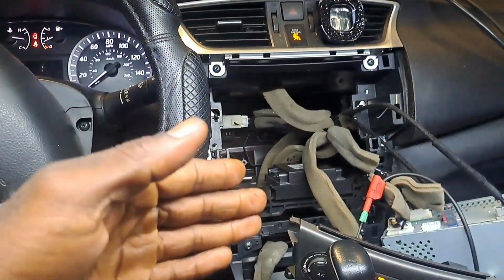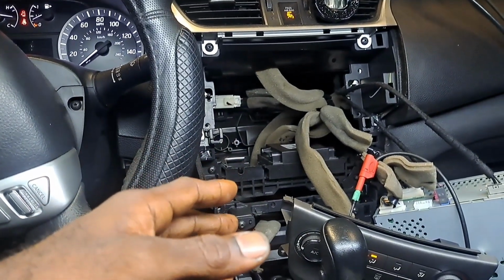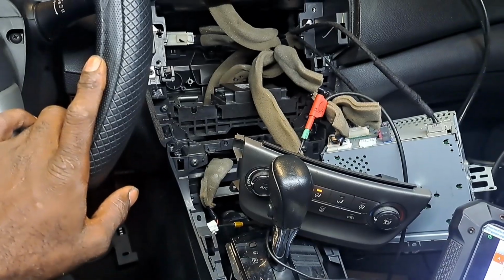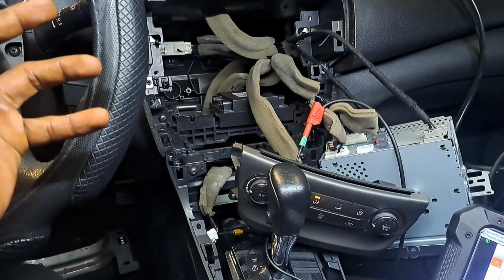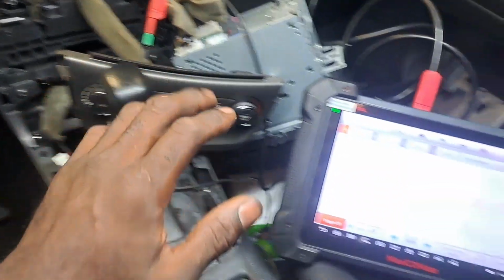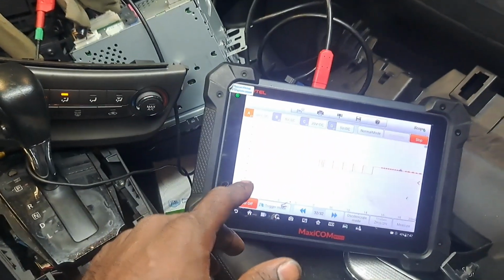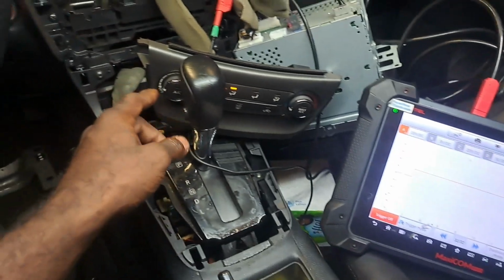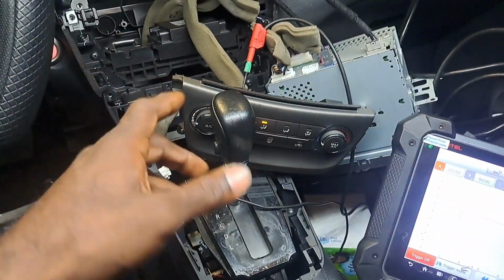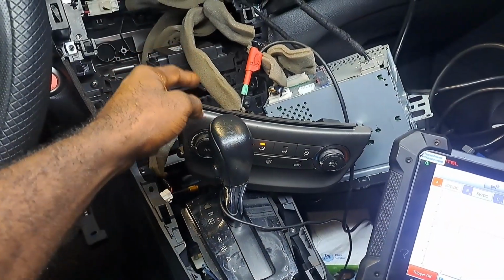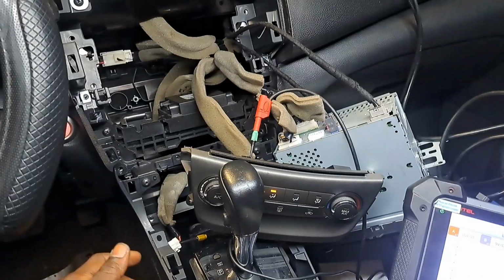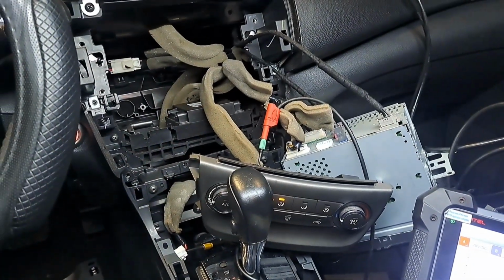Tomorrow, I'm going to grab the used part. And like I said, I'm grabbing both of those. I've got to try it out because I'm not seeing any movement on the CAN network. Would those pulses be influenced by me transitioning that speed? And again, I have that plugged in alone. It shouldn't cause that blower motor to work. So